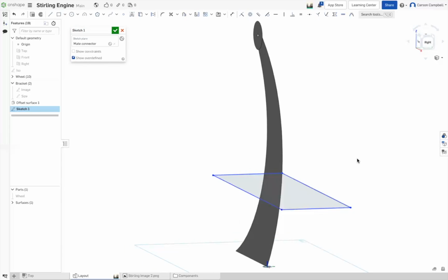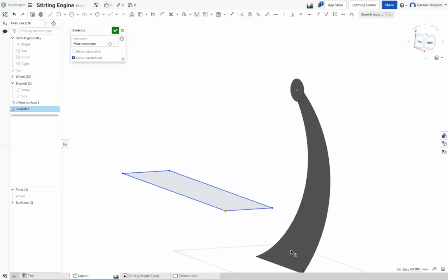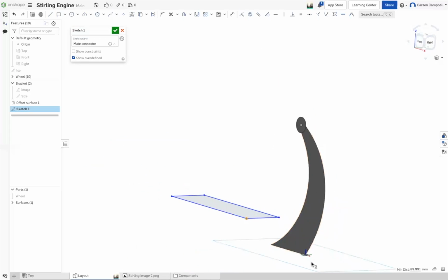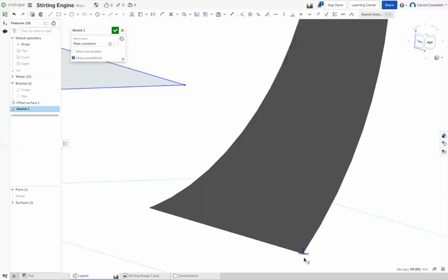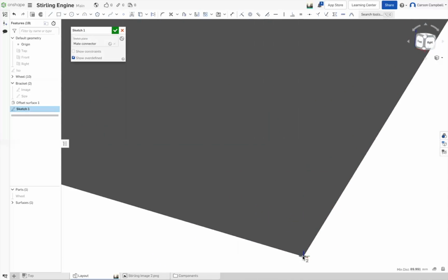Pick the vertex on the rectangle. You've got 4 of them, that's the one. Pick that one. And then go down and select the corner next to your, yep, down there. You need to rotate so you can grab the corner. And zoom in on that corner, and you need that vertex. It's probably going to fight you. Hit the K key on your keyboard.